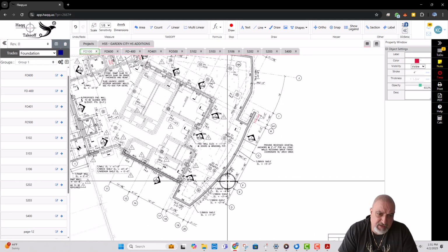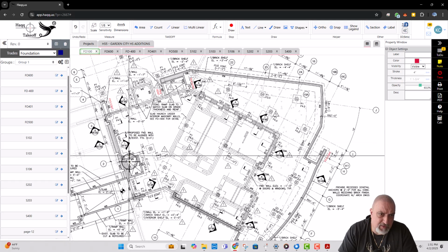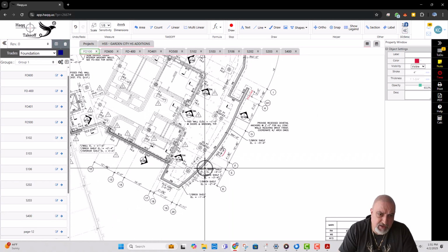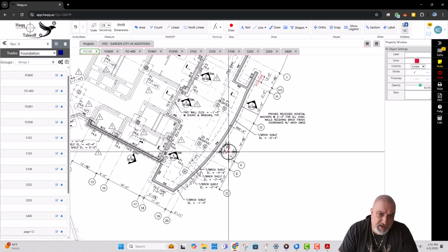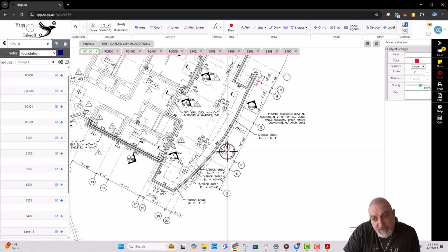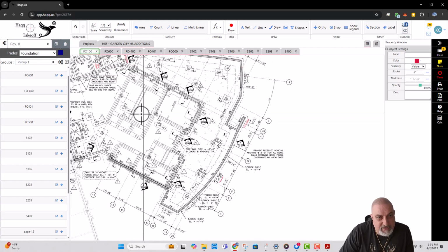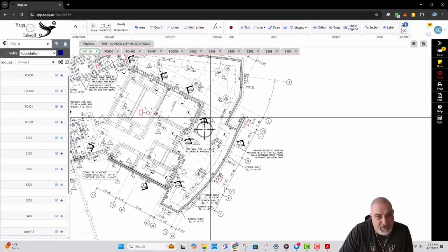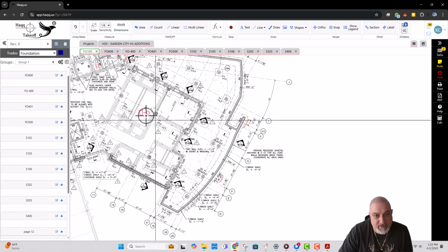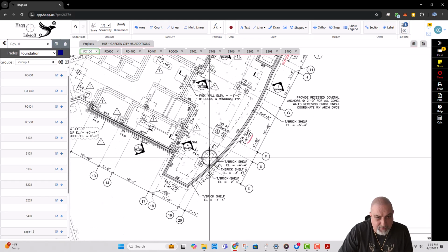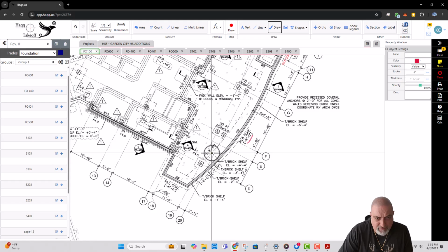Basically, I see, let me just quickly look here. I don't see deeper than, this is the deepest section. So over here, minus 9 foot. This is from this elevation given from top of slab, not from the grade though. Don't get confused. So top of slab elevation is here, 0 elevation. We're gonna take a look what's the elevation here, but it's given from this elevation. So minus 9 is our deepest location. Then it's stepping up. Here we got a step footing.